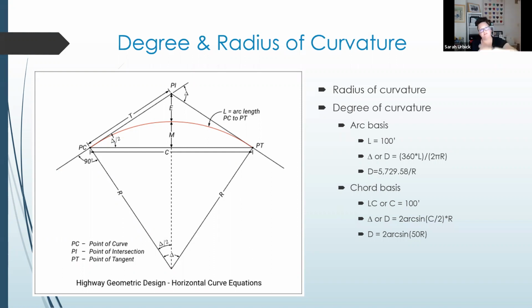That's where we leave that. We come back and hit that circle again, okay? So our point of curvature is where we take off, and our point of tangent is where we return to it. Even though they're both tangents to the circle, which means they are perpendicular to a radius drawn at that point, right? We get the 90-degree angle, as evidenced by it being drawn in there.